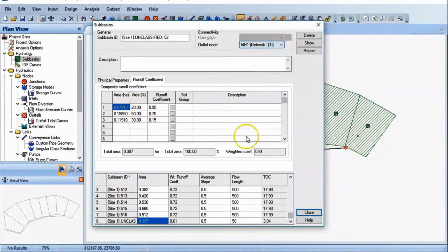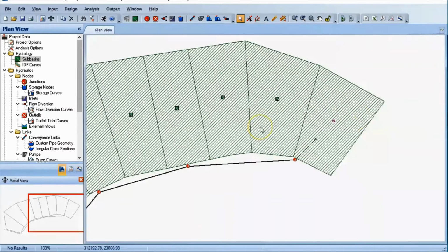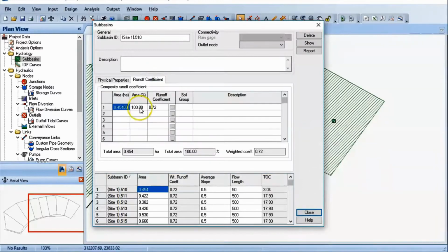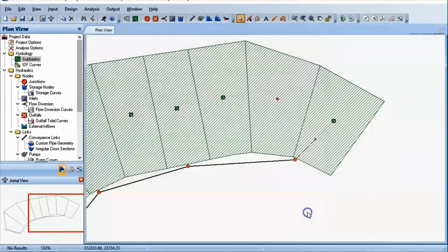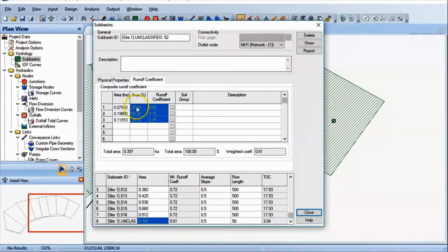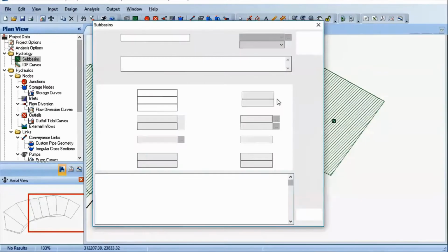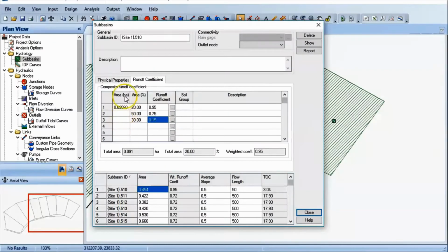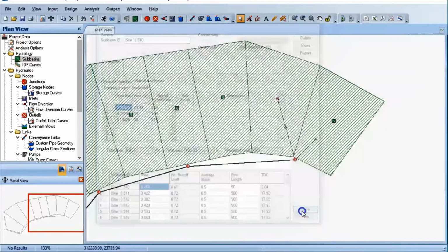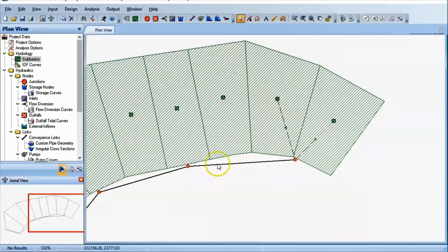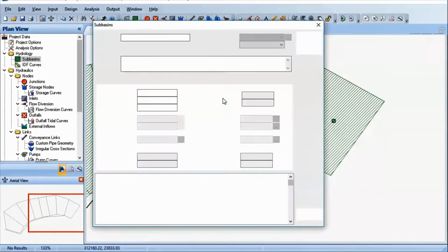Now, the tedious process about this is you need to do this for every single one of them. And remember, if there are updates required, it basically will make you do all of the steps over and over again. So basically, you need to define every set area again with the roughness coefficient. Now, sometimes if you did copy it over, it doesn't read it. So you need to still manually change these elements inside. So you need to link it to the actual inlet.